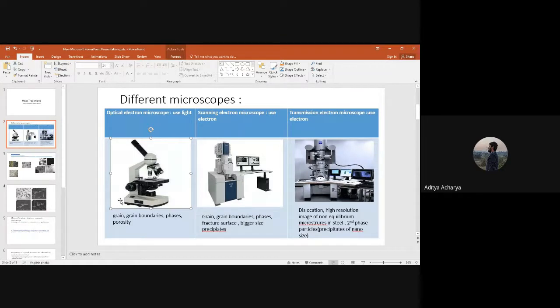Anyways, now we are moving to the next important part, that is, by using an optical microscope, what we can see. Suppose you have a steel, right? You do sample preparation before putting the steel under a microscope, right? You already know those things. You need to do sectioning, then mounting, then polishing, then finally fine polishing, and at the end you will do etching.